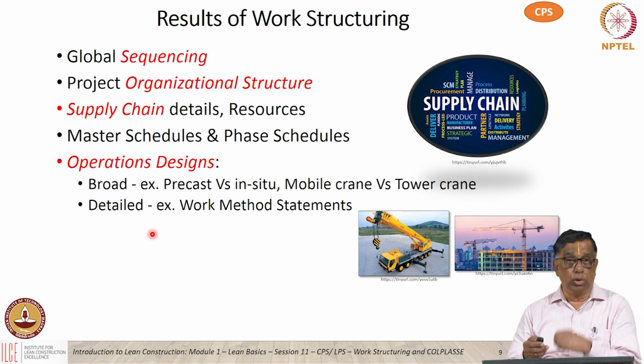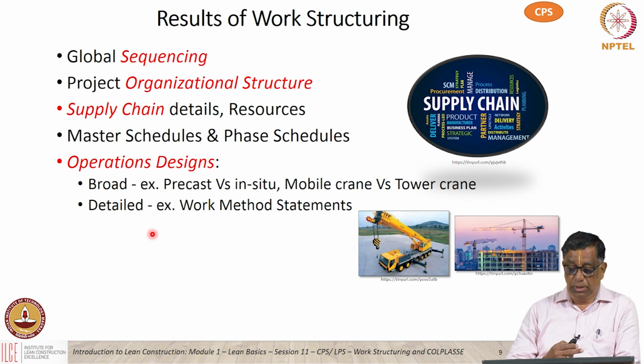So like I said, broadly we decide precast or in situ, then whether we need to use a mobile crane, a tower crane, a boom placer, whatever it is, and we also get the work method statements. The method statement is another important component of construction. Many people tend to ignore this important in-between step. If you look at the major international construction companies, they will not permit any work to be done unless there is a method statement in place and approved by the competent authorities.